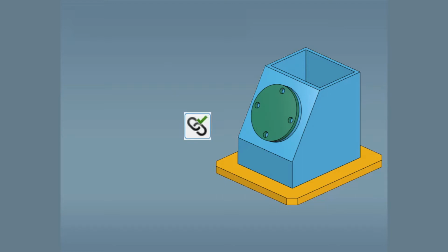If the external references toggle is clicked, the borrowed geometry will create links and maintain the references with changes. If it is cleared, reference geometry is still created, but the geometry does not keep pace with the changes. The second method, make component, lets you build geometry using sketches, sketch features, and fillets, just like working in a part, and make components from that geometry by converting it.